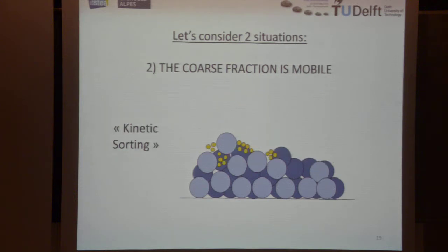The second mechanism I would like to discuss today is the kinetic sorting. We had a lot of discussion also this morning about this. When the coarse sediment is mobile, we have very efficient transfer downstream of the fine particles.